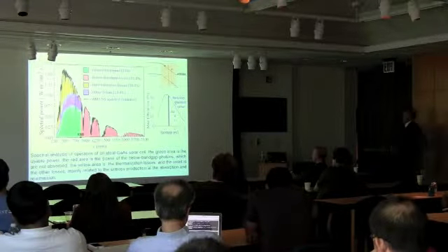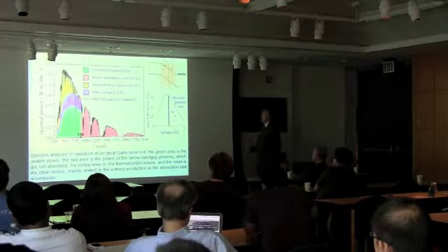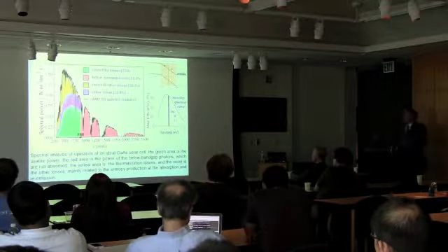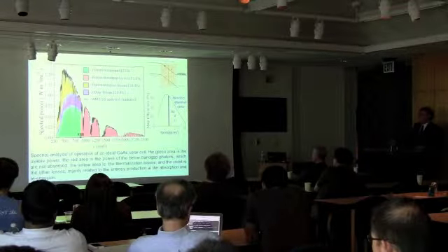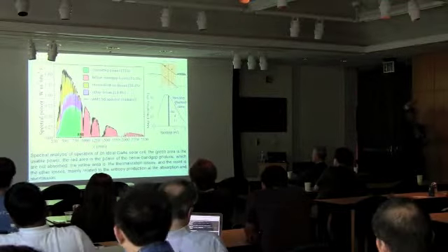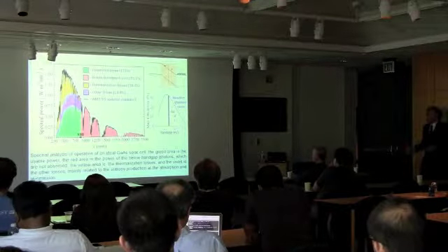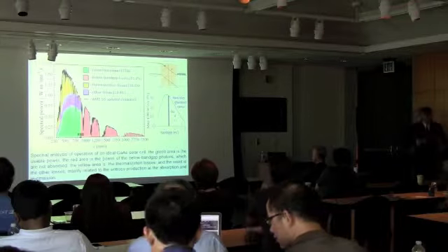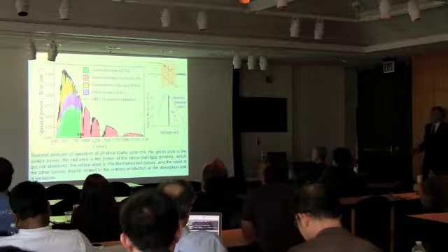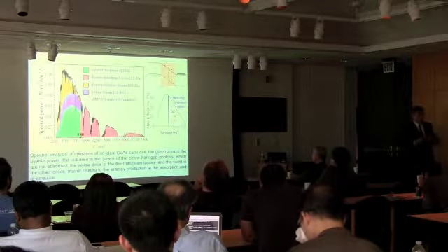Guaranteed. Then here it is also shown the thermalization losses. What do thermalization losses mean? You see that when I show the band gap, a photon that has a huge energy, substantially larger than the gap, also produces an electron and a hole. They are there, but what is going on? They will lose their energy by scattering and giving it to the phonon. So it is also inevitably lost energy. It's also 20% already out. There is no way that you will get those 20% back.